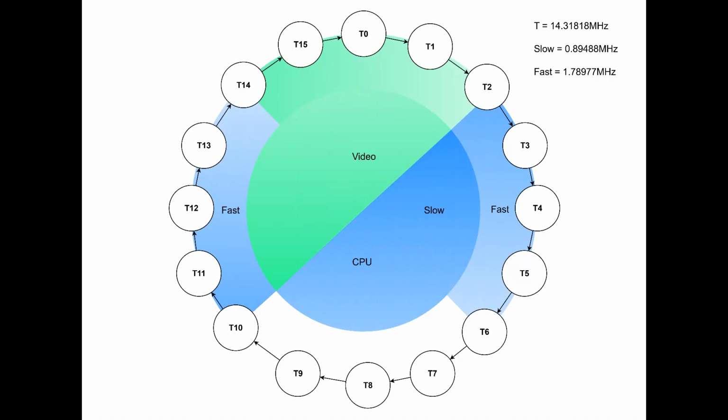I've converted that state machine to Verilog, because mixed language implementations cause simulation problems, and adapted it to suit my purposes. There are a few things going on here. The obvious is the quadrature clock and switching between fast and slow modes. I need to generate a memory strobe to latch the video memory for the VDG.